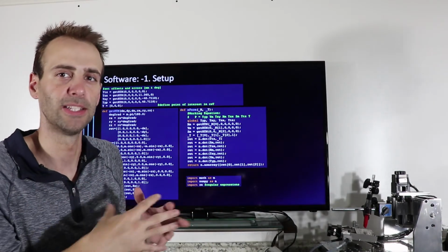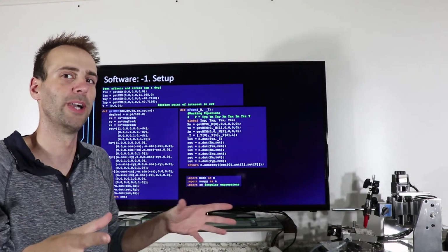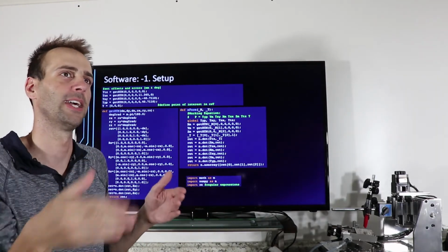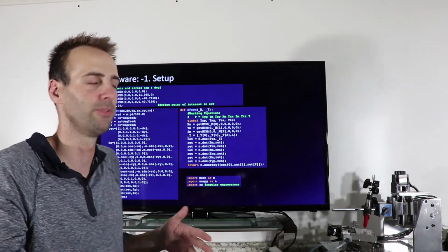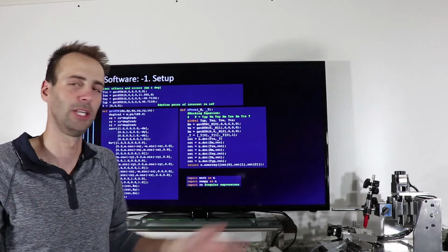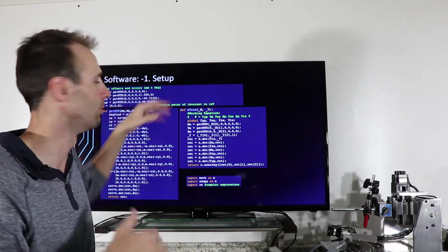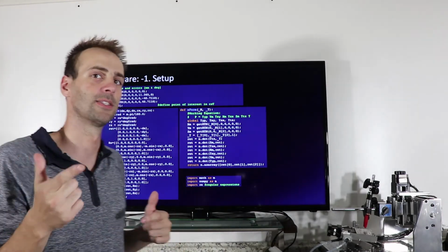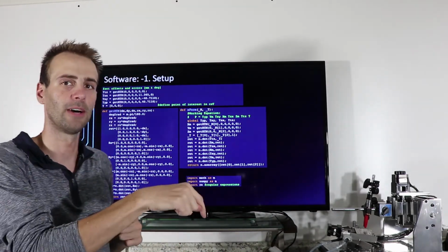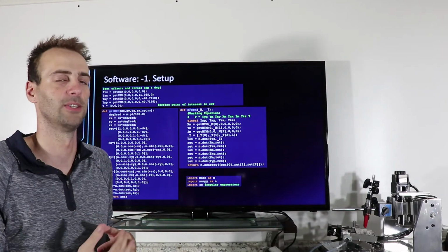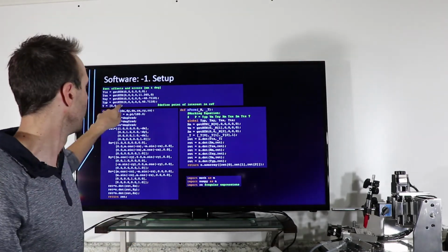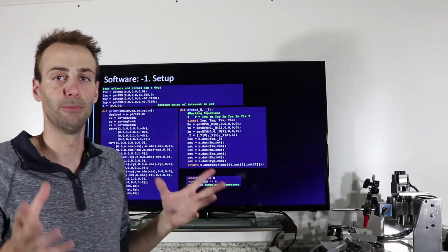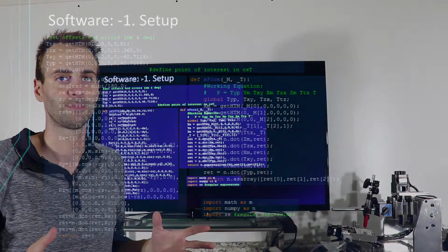That really means, on a Cartesian machine with no errors, when I want to move my axis, I just tell the X-axis to move. Here, on a machine that's not perfect, you have to do a little bit of thinking. So keep that in mind. Most post-processors already compensate for tool offsets for you, and that's why you have to pick your tool in there. So leaving it as 0, 0, 0 in most applications is fine.